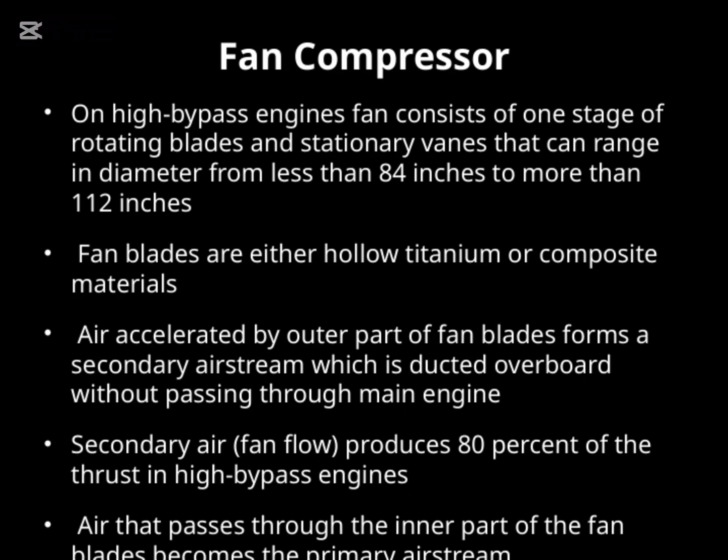Now, an interesting aspect of these fans is how they generate thrust. The outer part of the fan blades accelerates air, creating a secondary airstream that's ducted overboard without passing through the core of the engine. This secondary airflow is responsible for about 80% of the thrust in high-bypass engines, which is a significant portion.